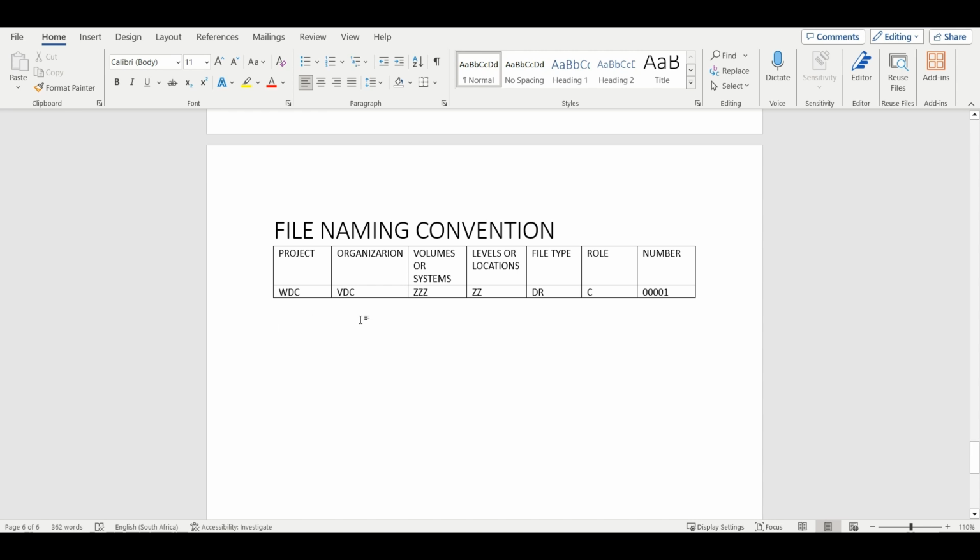And next one is the classification system. Usually when it comes to classification, the ones I usually go with are the Omniclass and the Uniclass classification. Due to the complexity and the extension of the project, the documents and drawings and files in the common data environment will need to utilize a standard classification system.